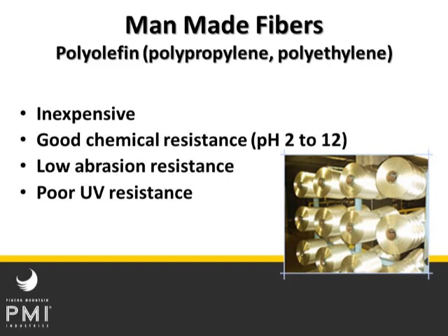It always amazes me to see this sitting out on the roofs of buildings where people are using it as life safety ropes for their guys on swing stages, and they're using polyolefin ropes that are just sitting out in the sun all day long, day after day after day. It really does degrade pretty fast in the sunlight. It's not really a great choice for that if you're around the typical sunshiny tops of roofs.